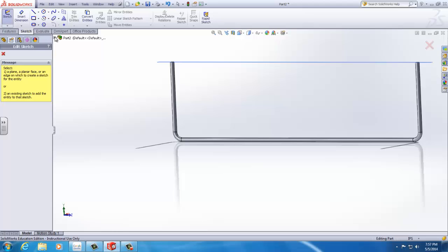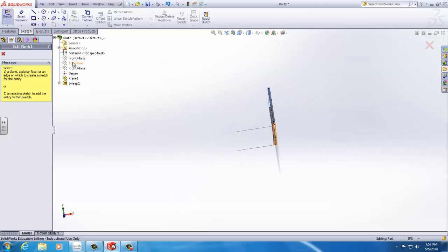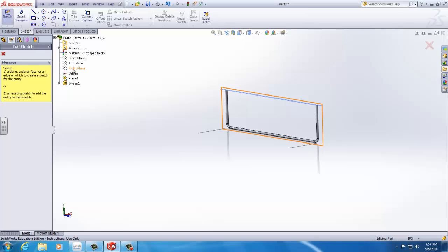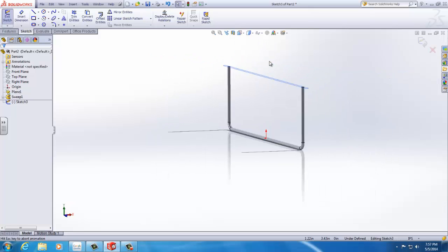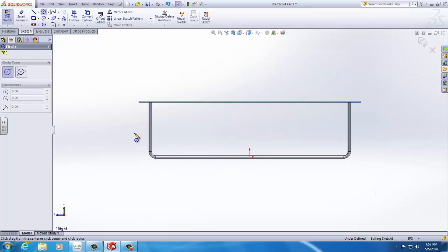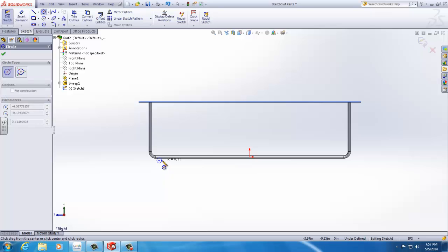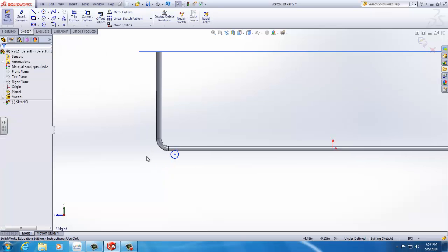I'm going to trim off so much here that I don't need on this right side. I want to make it exactly the same on both sides. So I'm going to use the mirror command. The center line is a mirror line. We're going to select these 3 lines I have here. Use the mirror about, and make sure that copy is active. And we select the center line to copy it over.